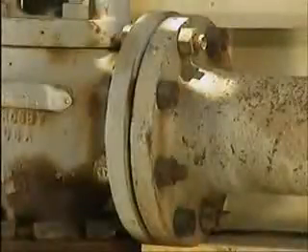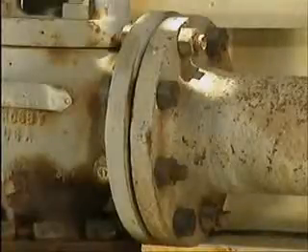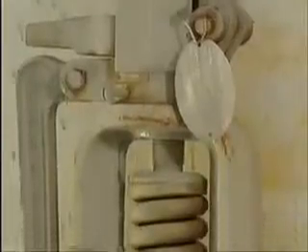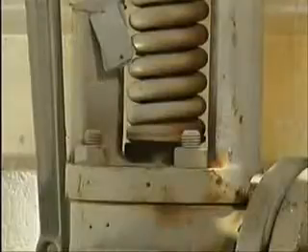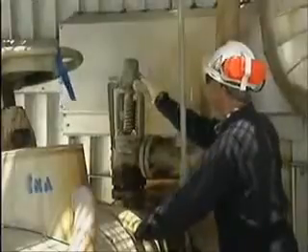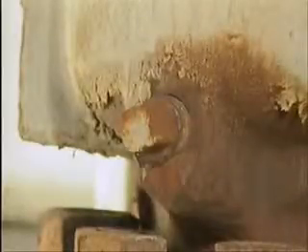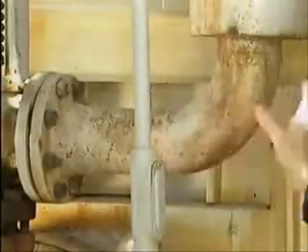Check for signs of leakage or leak-through at the discharge piping bolts and possibly around the yoke or bonnet bolts. Some valves have a yoke and a bonnet that are 2 connected pieces. Others, like this one, have a single piece that may be called either a yoke or a bonnet. For consistency, we'll use the term yoke. Also inspect the top or cap of the valve. Next, look for steam or warm condensate leakage around the drain plug and around the bolts on the yoke. Check the temperatures of the valve and the discharge piping.